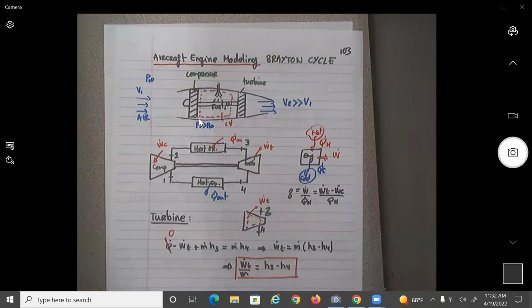So the pressure inside this section will be extremely high. Now, this is a control volume, and within that control volume at a very high pressure, you're going to put some fuel or gas and ignite it. So what you have over here is P, high pressure, times a constant volume, PV, plus some internal energy given by the fuel that you ignite, U. So here you have U plus PV, and you know that U plus PV is the definition of enthalpy. So you have very high enthalpy,